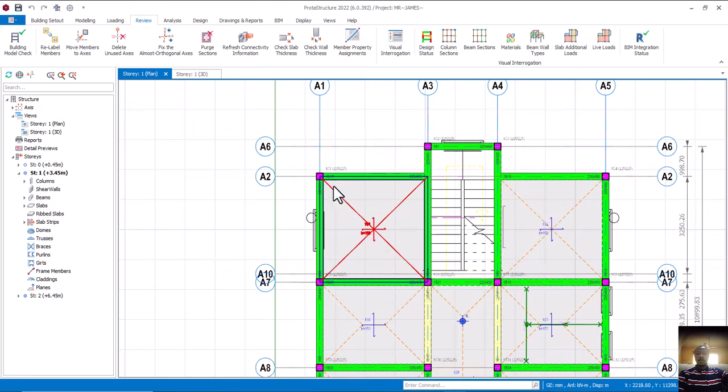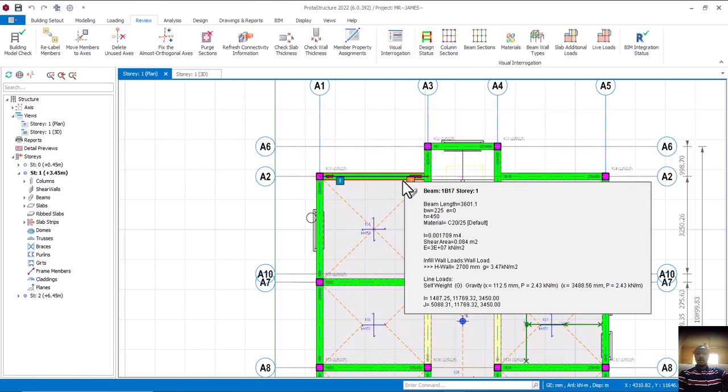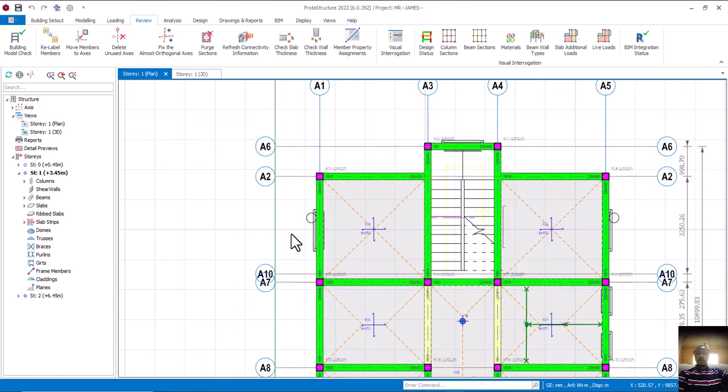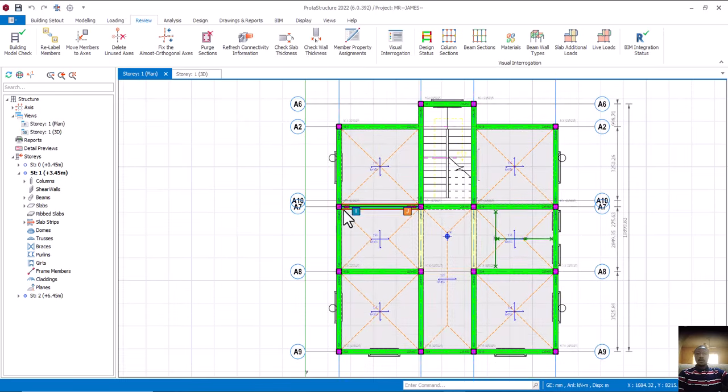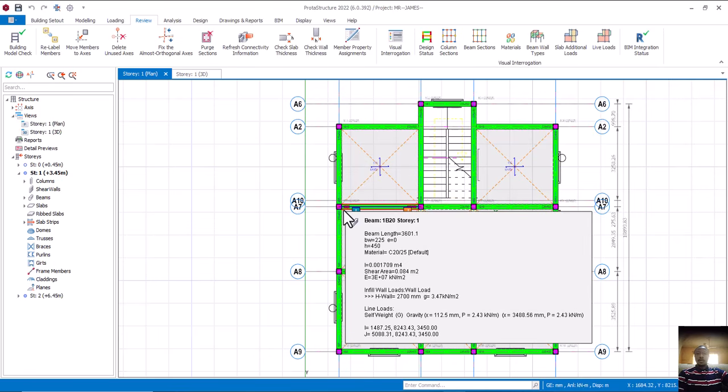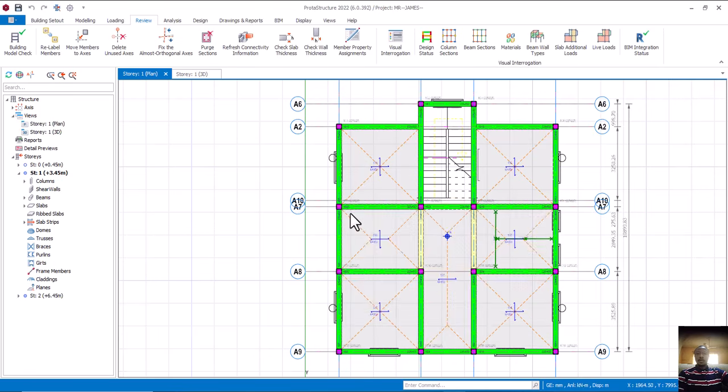But there are some places that, if you draw your bending diagram, you discover that it's not 0. So at those points, you don't hinge those places. Is that okay? Those places where the moment is not 0, you are not going to hinge it, because if you hinge it, it's very, very dangerous. That's why this class is very important, so that you know when to hinge, where to hinge, and when not to hinge. Is that okay? So as I have said, the moment at that hinged end becomes 0. So if you have the knowledge of manual design, it really helps a lot. Is that okay? So that is that.